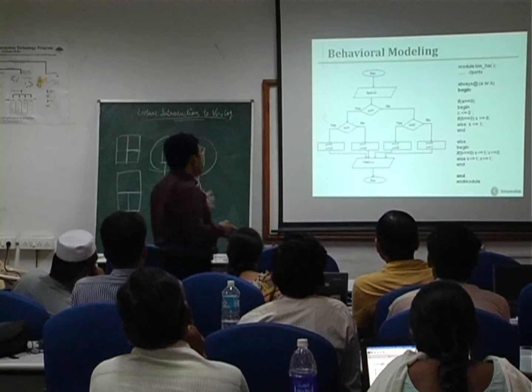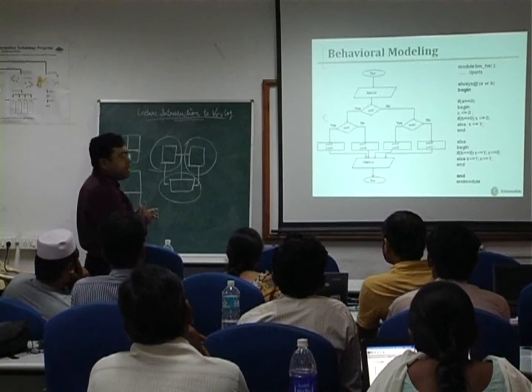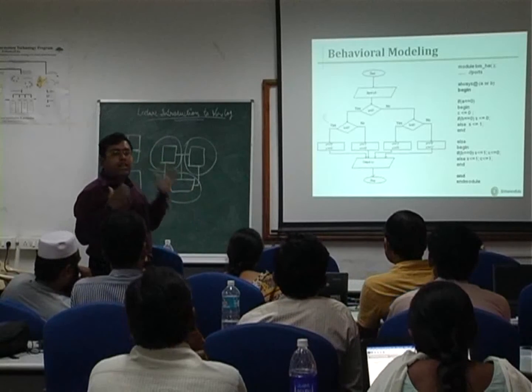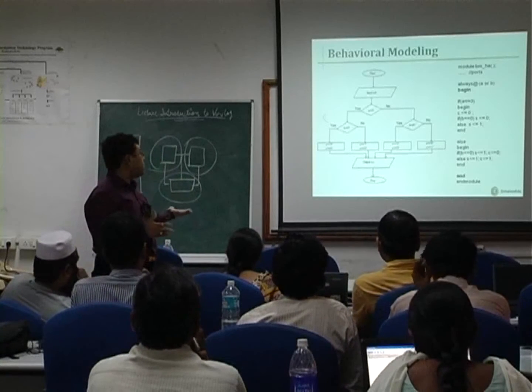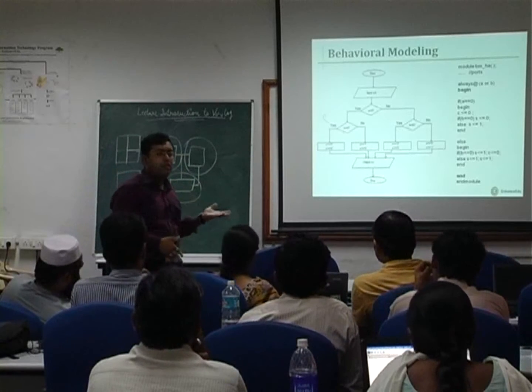Only one thing I need to say over here is that we are using this always @ syntax, so that we are having an event driven modeling of the system, so that if any event occurs, that means any change occurs in these inputs A or B, that is reflected at the output.